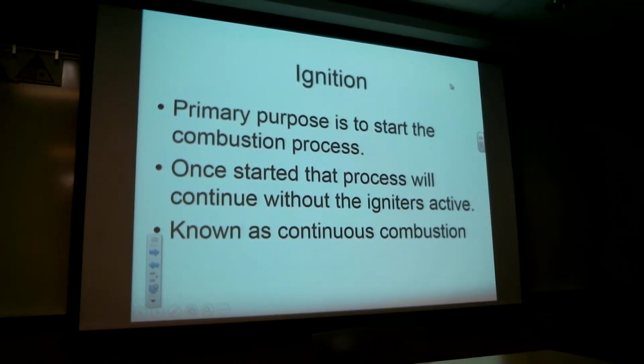So some of you are in my ignitions classes, and so every time you have an arc occur across a piece of metal, what happens to the surface of the metal? Metal transfers. You end up with metal transfer, right? Something happens to that surface. As soon as that voltage jumps from one side to the other, you're going to have some metal transfer that's going to start misshaping that metal. Now it takes an awful long time on an igniter, but it can kill the life of an igniter pretty quickly.